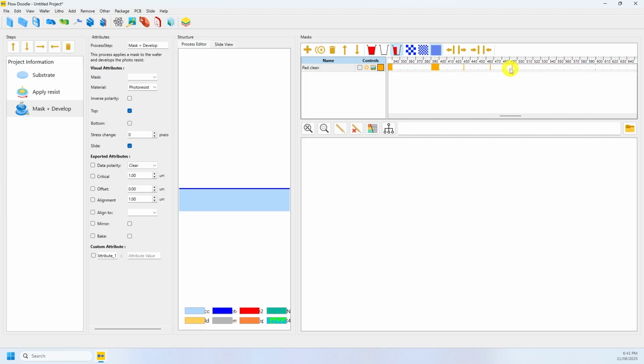You can also choose between Set Mask Pixels Dark, Set Mask Pixels Clear or Toggle Mask Pixel Polarity to control how mouse clicks affect the mask. Click the mask area to turn pixels dark or clear and create your structure.